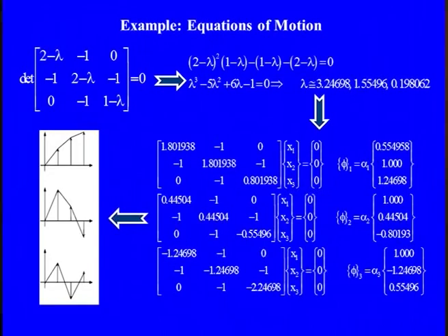And you see here now, if we want to calculate the mode shape, meaning the relative displacement, we can simply go to the basic equation and put alpha 1, alpha 2 and alpha 3 to see the variation of x2 by x1, then x3 by x2, and then x3 by x1. So, in these things again we have applied those basic features in the lambda.